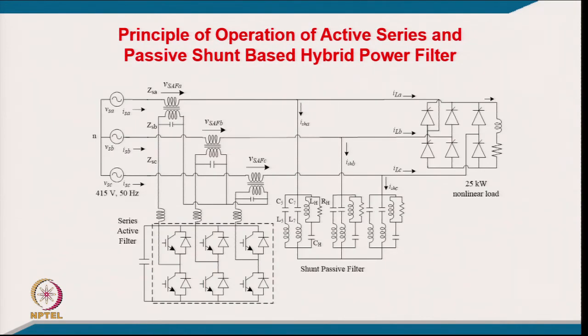And this is another quite popular topology, where you have a current fed kind of load, such as a thyristor converter, which may be an RL load, a DC drive, or can be driving a current source for your large rating synchronous motor drive. There are plenty of loads of such nature. So, a major amount you are putting in like a passive filter here, and you are not disturbing the current fed kind of load because you are connecting in shunt.